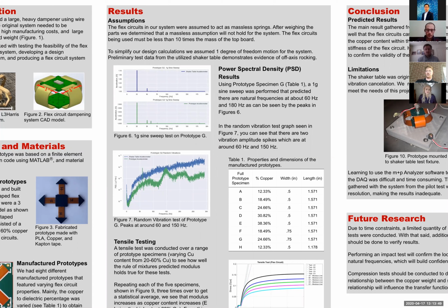And one of the main reasons that we had poor data at first is we were testing between a range of around 0 hertz to 20 kilohertz, which in reality, we only wanted to see things maybe between 0 to 300 hertz or even lower. So we ended up with extremely low resolution in between the values of the hertz, because the table is just not able to gather data in that big of a range in a very fine way.